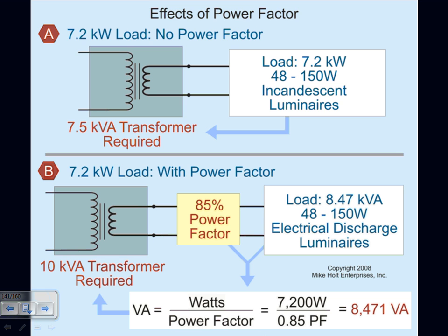You're going to ask me, Chad, what's the power factor for that baby? I want to tell you the power factor is 90. Now you take the 88 watts for that baby, divide it by 90. You find the volt amp, and then you start adding them on the circuit. We do not size by watts. I can't drive this enough. I want you guys to get this message: we size things based on the volt amp, not the watts.